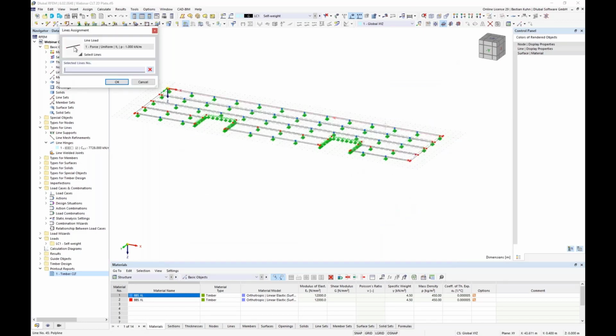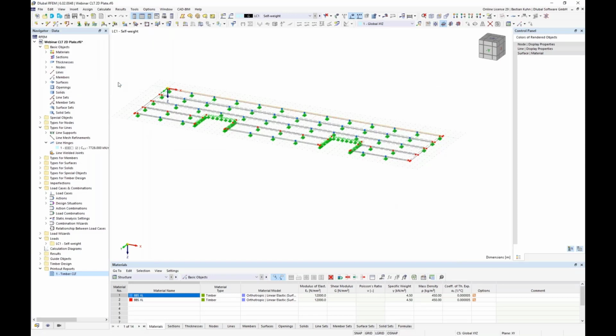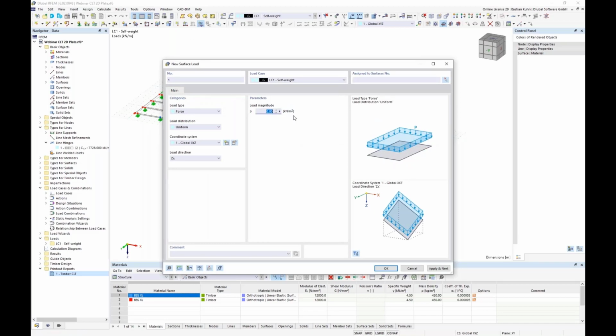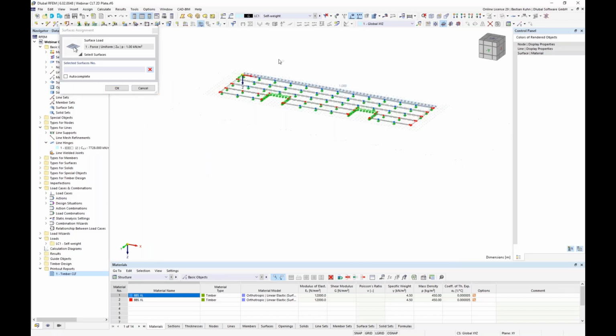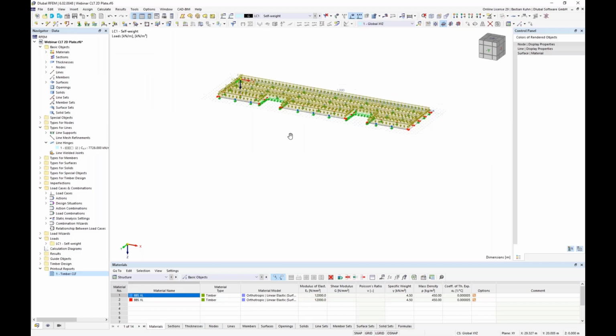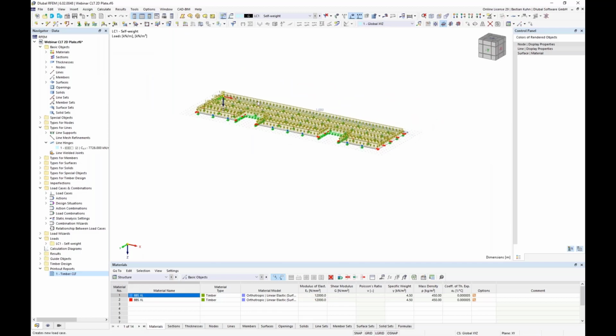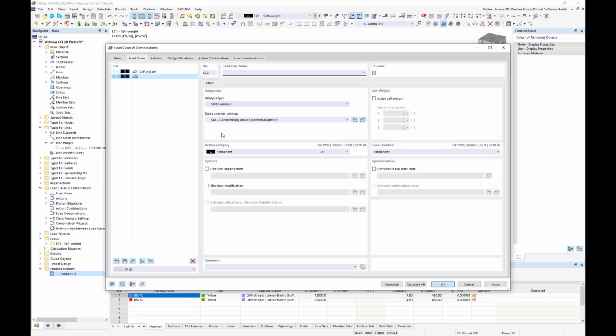If you have looked at the building, it is standing in most of the highest earthquake areas around the world, so there's probably more force than 1 kilonewton per meter. Also from wind, there's probably more force. But yeah, maybe we are in the ground floor here and just have some small force. Yeah, we also take a small value in the load case 1 from self weight and say okay, we have that here. And now we define for each plate a live load.